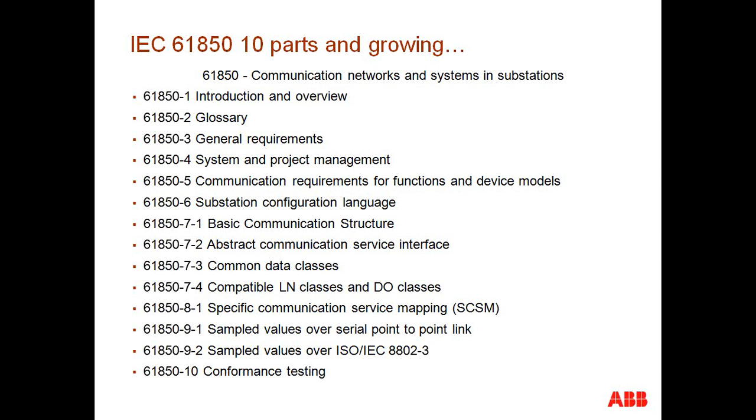Okay, we have a question right here, so give me just a second to read it. One question that we just received: can IEC 61850 be used with all IEDs? The answer is yes, as long as the IEDs, relays, or pieces of equipment that are going to be part of the network support IEC 61850 as a communications protocol. And most major vendors of at least protection and control relays do support this particular standard.